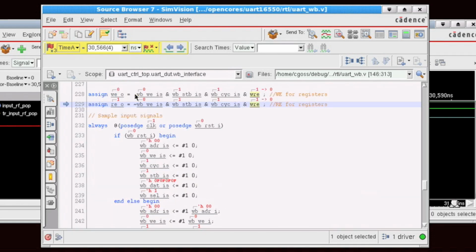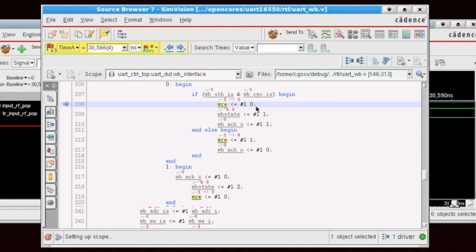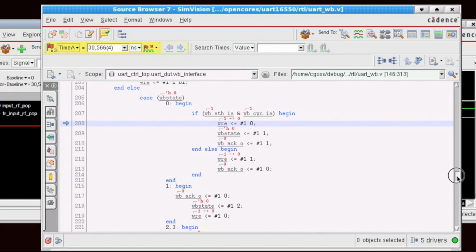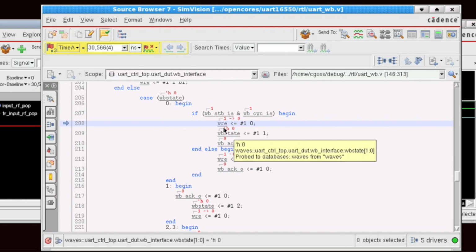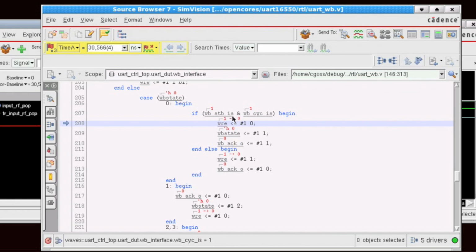So I double-click on that signal, and this takes me to another signal in the list. We see we have an assign statement, but again, one of them is highlighted, only one signal is transitioning. This is the most likely contributor, so I double-click on this. Now we're taken to a scalar assignment. And now we have to do a little bit more investigation. So I take a look in my source and I see that I have a number of different signals that I could explore. I could explore why any of these 2 signals in the if condition are set. I could explore potentially why this case statement is being set. Maybe I might need some guidance here though, in terms of which one I should select. I don't want to go down any dead ends.